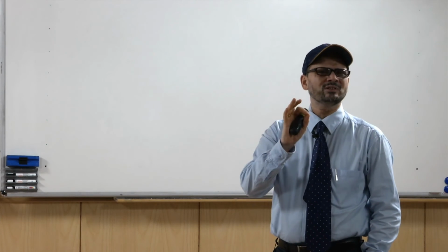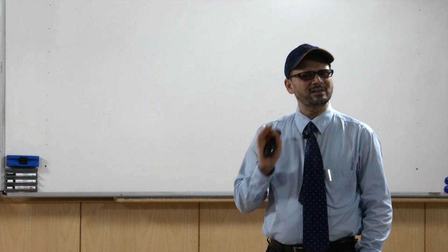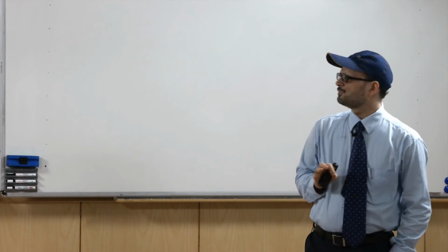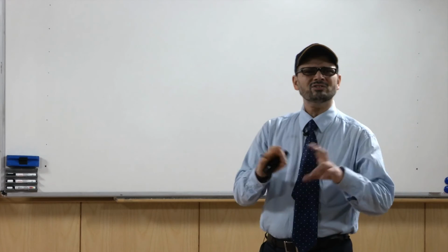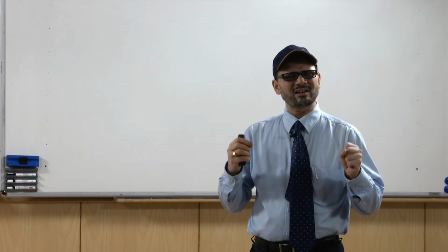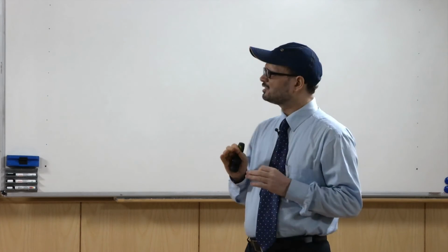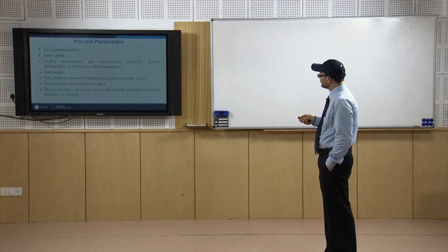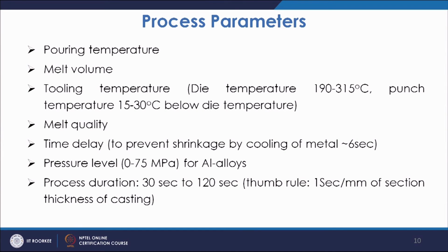If the melt volume is less, then there will be underfills, the cavity will not be completely filled, and if it is more, then there will be losses, it will go as splash, or if not, then it will create a large amount of pressure. So, melt volume has to be controlled. Tooling temperature, means you are basically keeping the temperature.